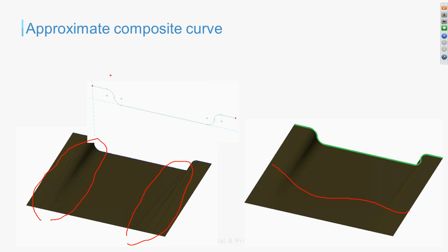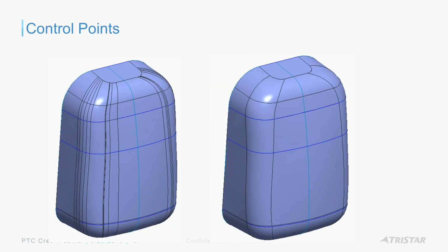The way that I'm doing this is essentially converting my curve, right? So when we designed this original curve, or when we sketched this curve, I'm having quite a few entities, right? A straight line, curve portion, etc. But I could convert that into a curvature continuous, or a C2 curve, and then do the blend so you won't get this. So it's a nice little feature when you do the copy paste to create the composite curves. And also control points, right?